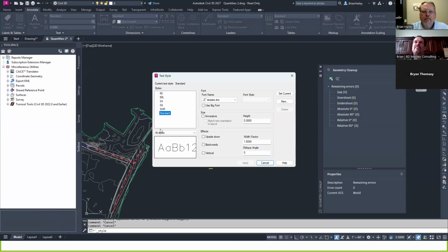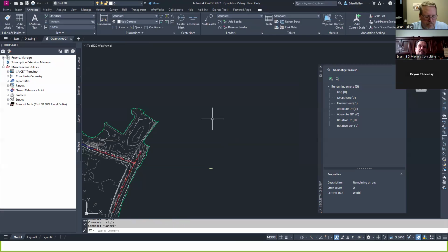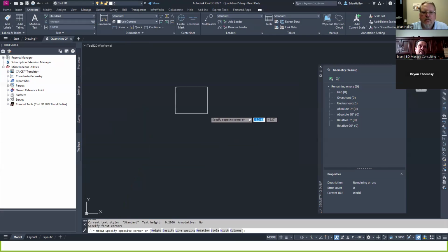All right. So the default AutoCAD stuff that ships with Civil 3D, you'll notice the text styles are using SHX fonts, right? Based on my understanding, and I could be completely wrong because I don't think I've ever heard anything official, the SHX fonts are a throwback to the times when AutoCAD couldn't handle fonts. So AutoCAD created their own fonts, these SHX things, which were basically just lines that were letters. Remember, AutoCAD was also built on DOS, before true type fonts even existed.